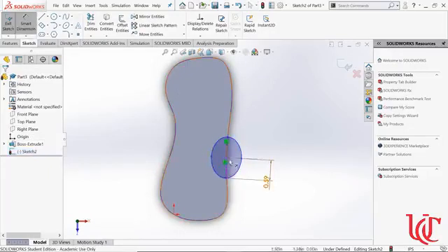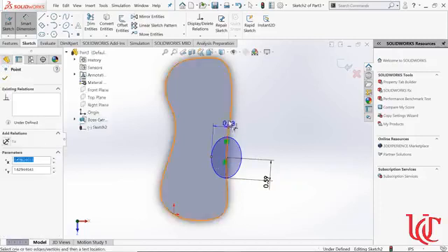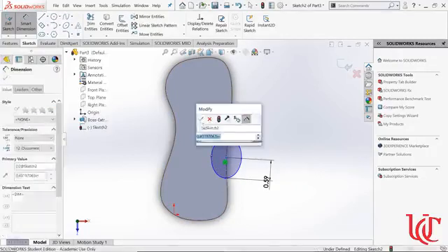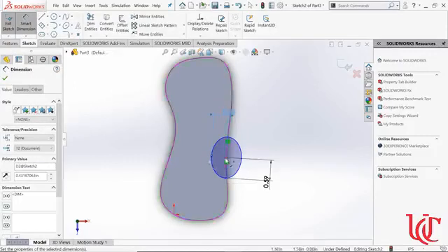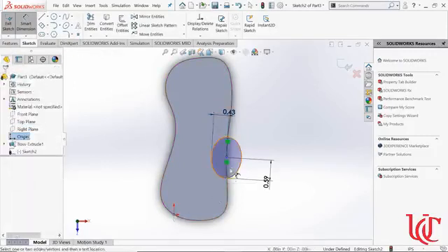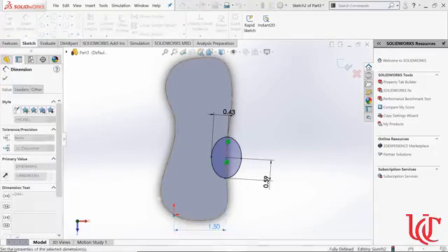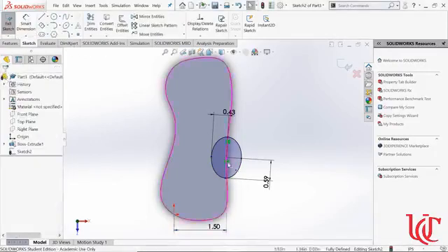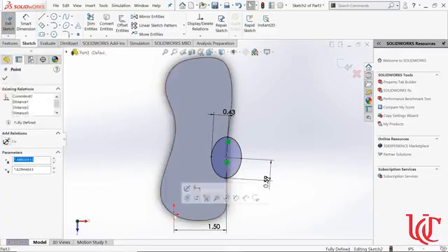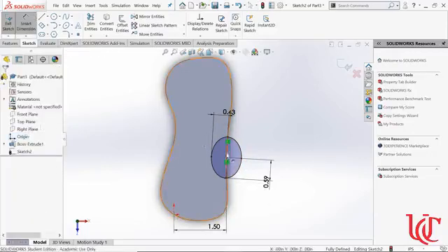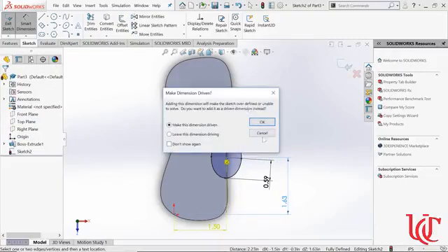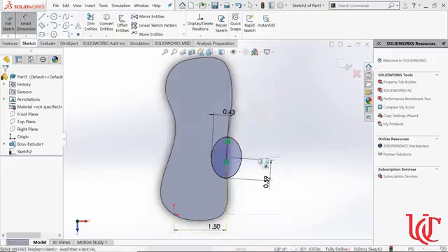So that dimensions my major axis of my ellipse. I need to dimension my minor axis, for example. So you might have ellipses or curves in your design as well. And it also needs to know where this point is from the origin. Okay. Once it got that, it was actually fully defined because it knew something else about that point y distance-wise. You may have needed a y distance as well, but if I try that with mine, it will probably tell me that this is overdefined. You always want to say cancel if that happens, not accept that.